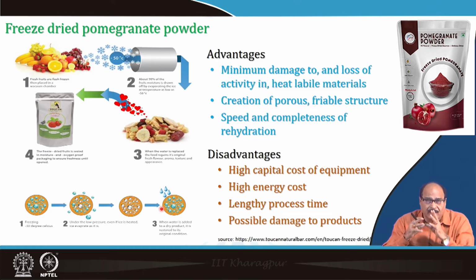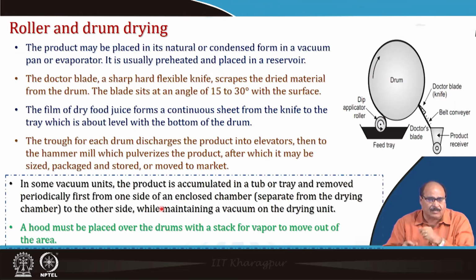However, the major disadvantages are the very high capital cost of the equipment, high energy cost, a lengthy process time, and possible damage to the product, particularly if the freezing is not properly conducted. Some structural damage may occur, otherwise there is no heat damage, so the quality is very good. It is normally limited by the cost problems. It is used for very heat sensitive materials and high value commodities.